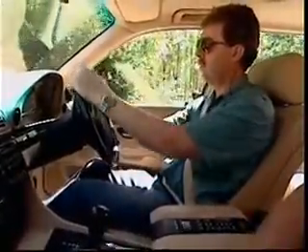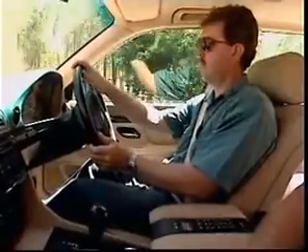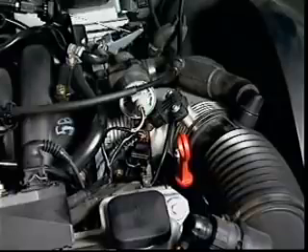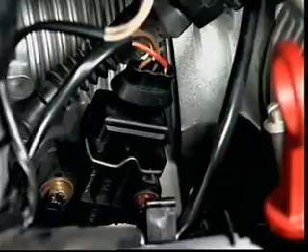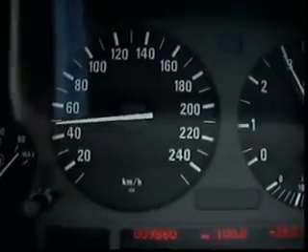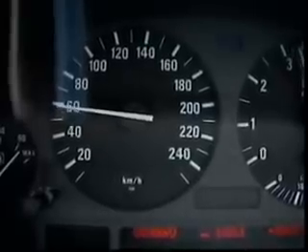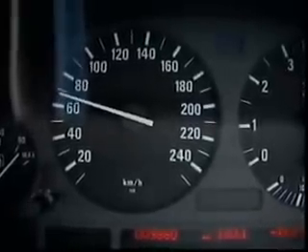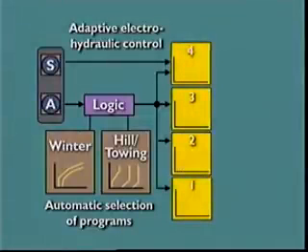Accelerator pedal movement can be evaluated when moving the vehicle away from rest and during regular driving. The length and frequency of kickdown periods can be evaluated, and the speed of accelerator pedal movement, or kick fast. This data from a throttle position sensor, together with vehicle road speed, can identify driving style. One of four shift programs can then be initiated.